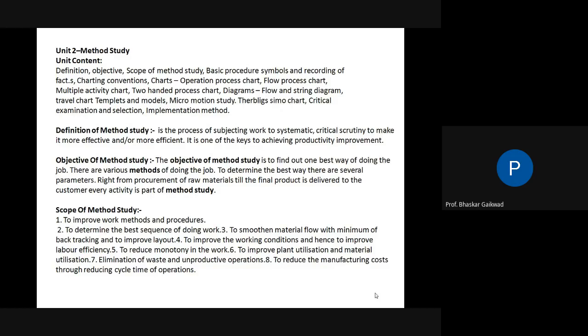Suppose blanking and piercing are different operations, so different tooling, a different process and separate manpower are required. Instead of this, is it possible to do the blanking and piercing operations in one stroke of the machine, so that one manpower and one machine give higher output? So we systematically study the present process and find the area because of which the manufacturing cost is increased.